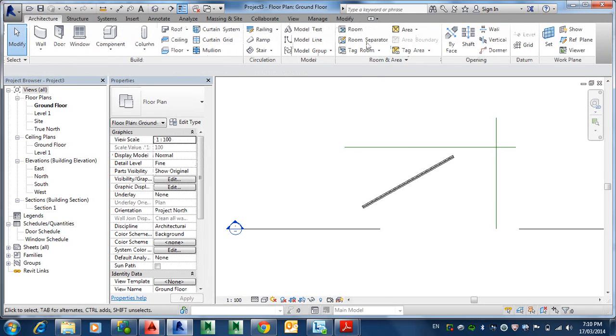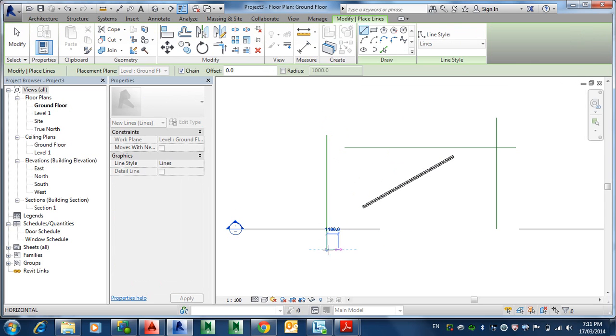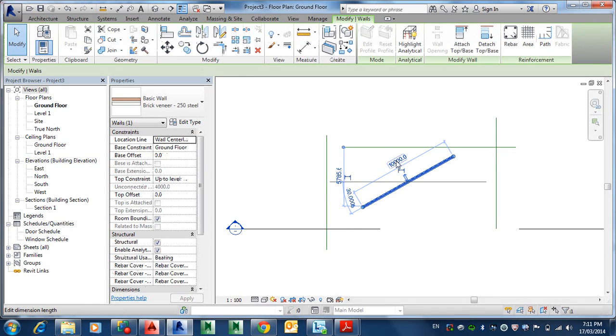Oops, what am I doing? I'm using AutoCAD in here. Not a good thing. There's no enter. Let's escape that. If I want to grow this thing, I click it, and I'll make it from 10 to say 15 meters. What's wrong with this number lock? Let's try it again. By the way, for 15 meters, you can actually type in 15 M in here.